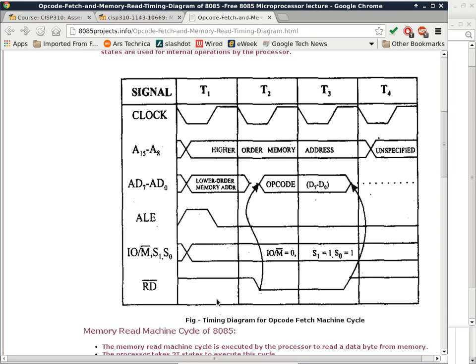Now, since we're talking about having multiple buses and customizing design to make the throughput improve, there's one easy design to improve this whole situation. The von Neumann architecture is basically saying your data is residing in the same memory as your instructions. Your opcode is coming from the same book, basically, as the data. And that's why it becomes a bandwidth limitation, because you have to read the instruction from memory, but whatever data you're processing is reading from the same chunk of memory using the same bus. So you have bus contention all day long because of that.